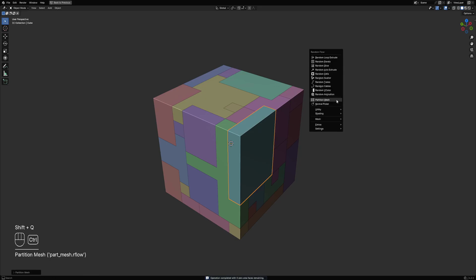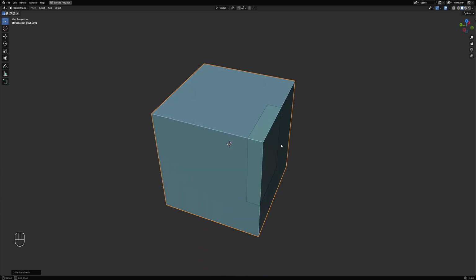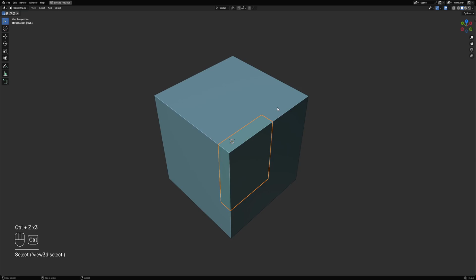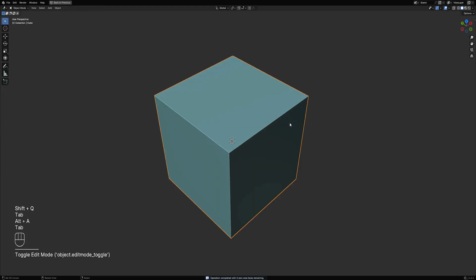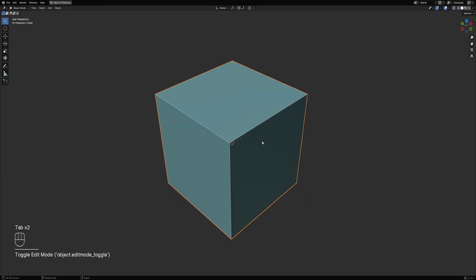Then click and it will unify that area, but will not do it for this. To include this in the unification, we need to select this. If you happen to partition the already partitioned part, then you have to select it and then another piece of the originally partitioned mesh, then you can include it in the merge operation. That makes sense.